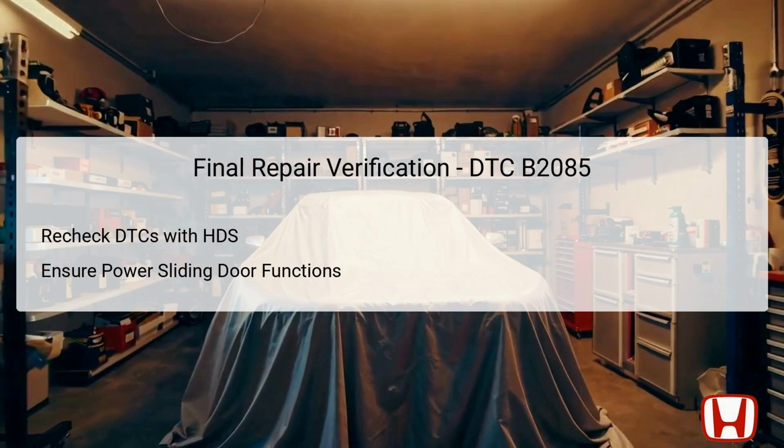After completing the necessary replacement of components identified in previous steps, it's vital to conduct a final repair verification. Start this process by rechecking the diagnostic trouble codes using the Honda Diagnostic System, HDS. This step confirms that the error code, DTC B2085, does not reappear after repairs have been made.